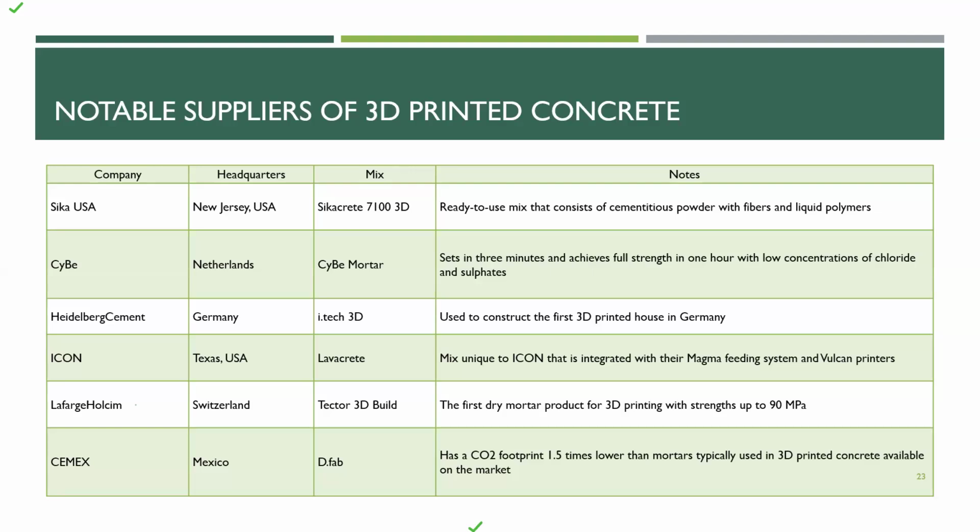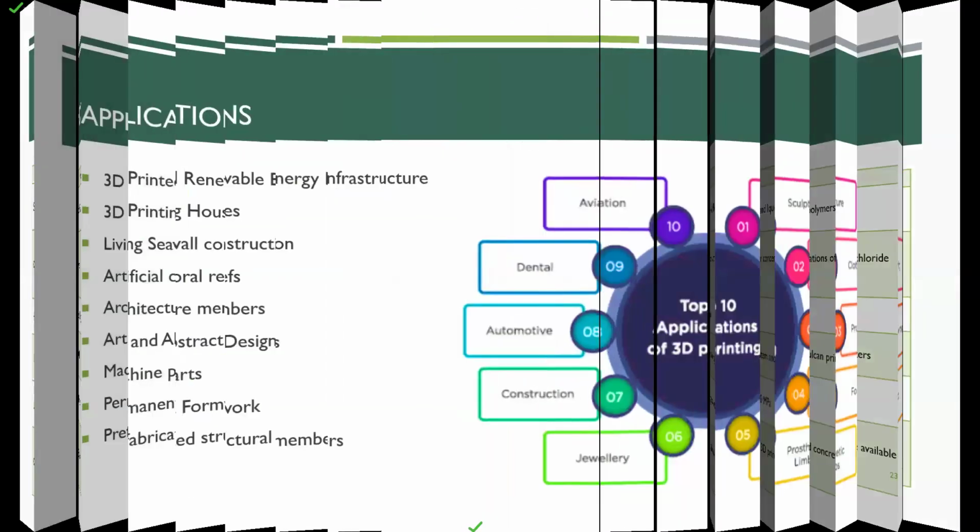Because for SIB, the extrusion speed is like 2000 or 3000 rpm, so it extrudes very quickly, and you need a material which hardens very quickly, like 5 minutes setting time or 10 minutes setting time. So for that, they give their own ready mix materials in powder form. You just have to add water and use it. In research areas, we are trying to prepare our own as well, but these are the notable suppliers of the 3D printing concrete material which they have prepared.